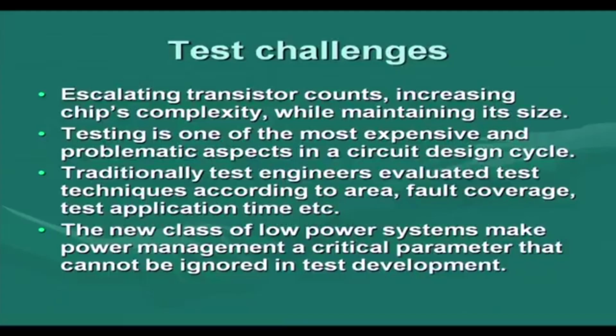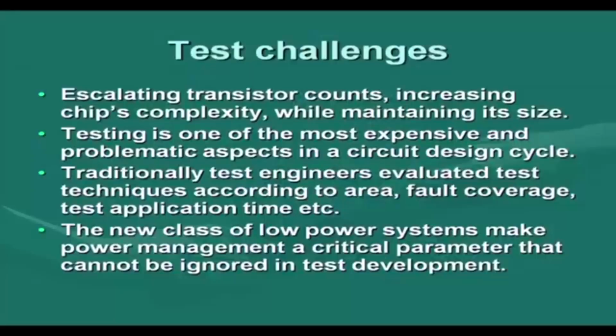test pattern set. But these low power systems make power management a critical parameter, because low power systems will have a power budget. So, you cannot go beyond a certain power consumption. Normally the designer will tell the power budget for a system, and it cannot go beyond that. So, as a test engineer, we cannot apply patterns such that the budget is exceeded. That way, power management becomes an important part of the testing process also.